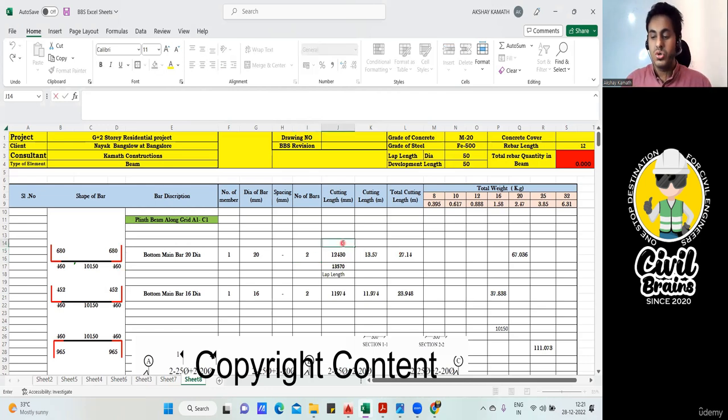I'll do it here now. So the total cutting length will be this 680 plus 460 plus the clear span 10,150, plus this 460 on the right side, plus this vertical of 680. How much will it be? Press enter. Finish. So 12,430 is the total cutting length that is required.